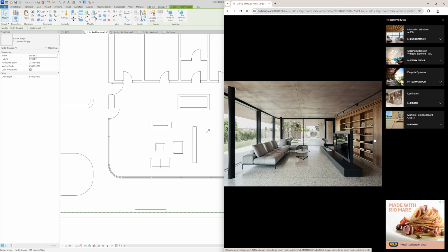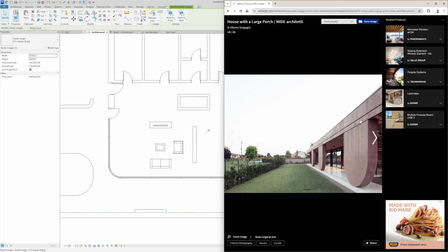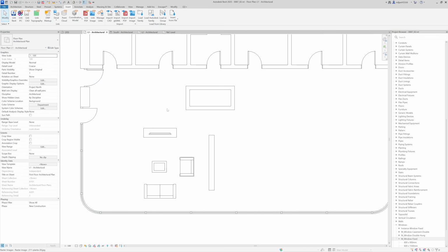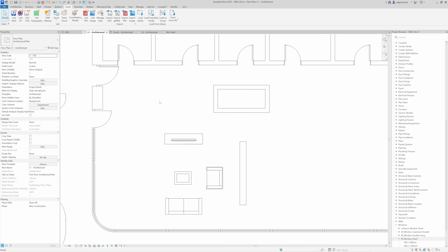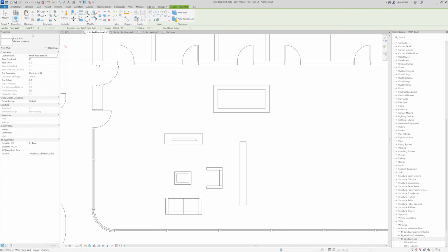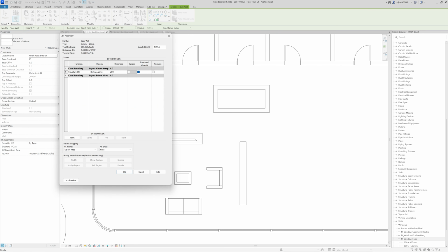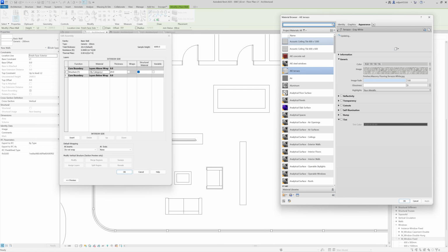And what we can do next is to make this wall in the back, so I'm just going to make it very quickly because I have a lot of information. So what I'm gonna make for this, because probably there are cabinets here, so the easiest way for you to make it will be just to create a new wall type, let's say 20 millimeters, and then I'm going to add some wood material.